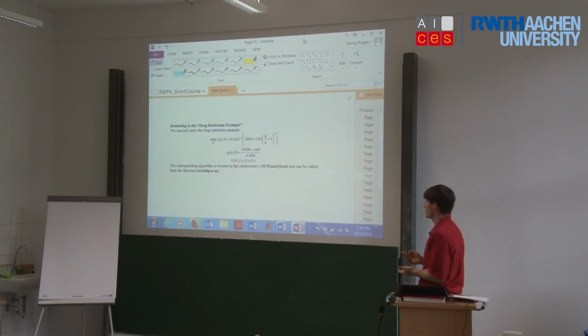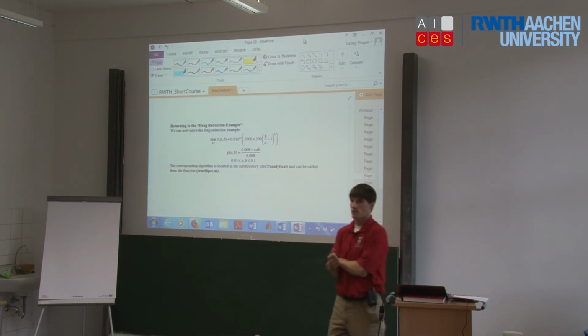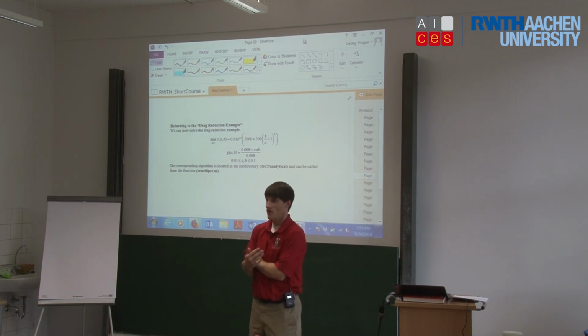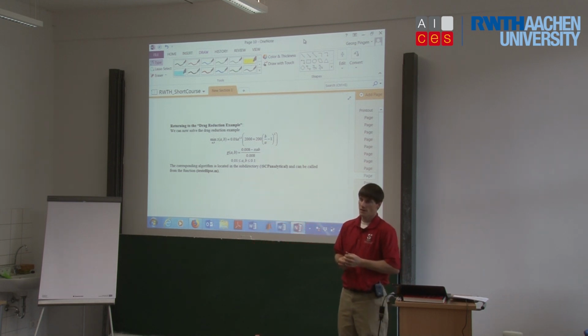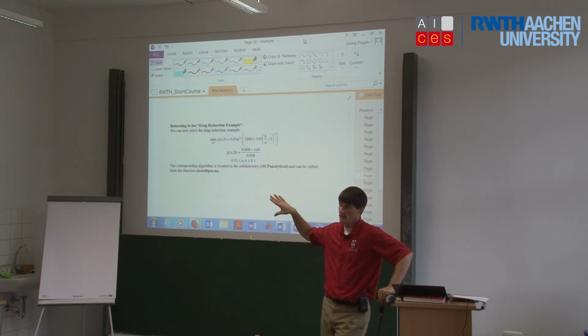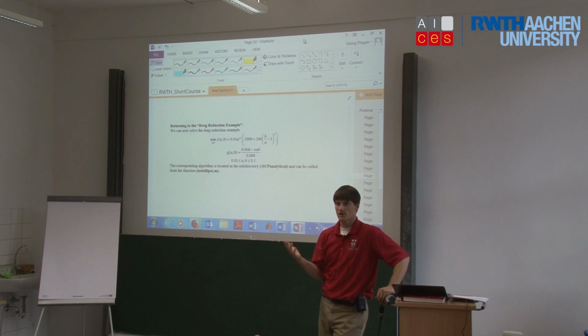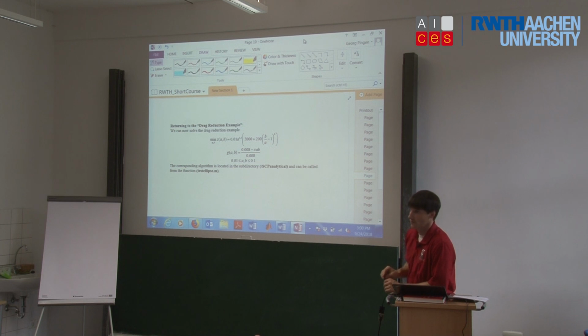So now we have our optimization algorithm, and as I discussed with some of you in the break, there are by all means alternatives to the SCP algorithm. The SCP can also sometimes, you might observe a problem where it seems to converge towards an optimal solution, but it doesn't hit the convergence criteria. If your convergence criteria are too stringent, it might not hit them, and it will then continue past the optimal and start diverging. That's something I've experienced as I prepared my materials for today.